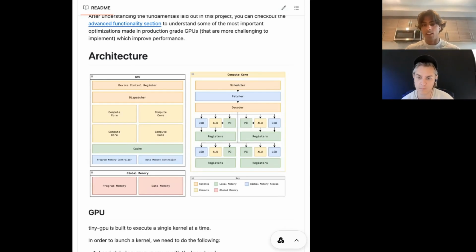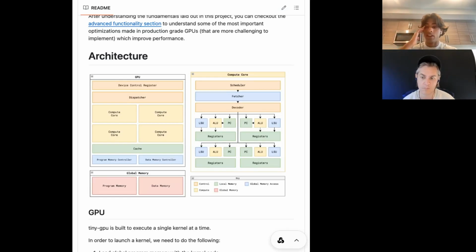And the important hardware thing is, in order for that to happen, what that actually means is that those register values, in this case, and this is what I meant by it being a bit of a simplification if you can explain important things with it, the register values are 16-bit register values. They store 16 bits. In real GPUs, they have a whole host of registers. They have registers that can store floating point 16 and 32-bit numbers. They have scalar registers, and they also have vector registers. So in the hardware, you would actually have registers that store 1-bit or 2-bit values, and that's going to be way faster. That's how it gets implemented in the hardware. But yeah, that's pretty interesting.